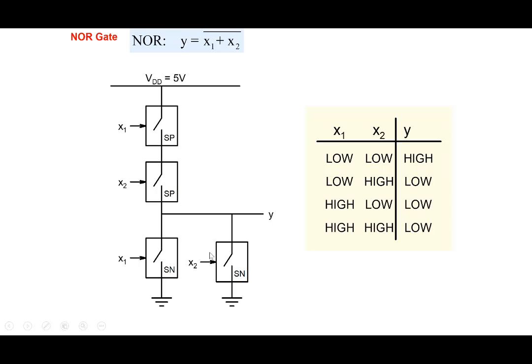And similarly, think about it: given an OR gate, how can you implement an AND gate? If you can do an AND operation, an OR operation, and a NOT operation, the inversion operation, using any particular gate, that gate becomes a universal gate. Because with that, you can do anything. You can implement any Boolean expression, any truth table.